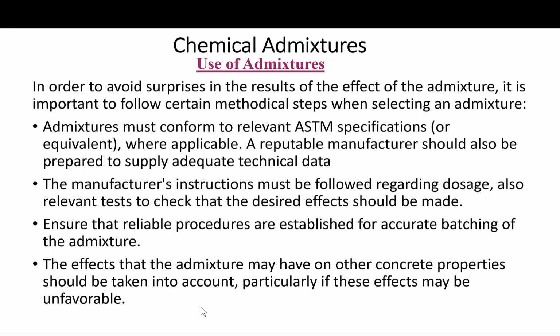Also, the recommended dosage under certain identified conditions. So the recommended maximum dosage and the effects of overdosing. Those are the key elements that the manufacturer of an admixture should furnish to the engineer or to the ready mix supplier in order for them to be aware of the limitations of such an admixture.